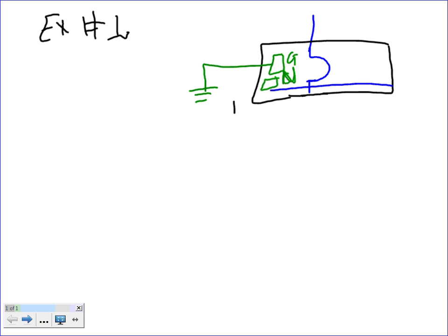Equipment grounding conductor. I'm going to use another color to take the neutral back. This is my neutral. This is my phases, 3 phases. I need to size the bonding jumper between the two. You can see that bonding. This is my main bonding jumper.